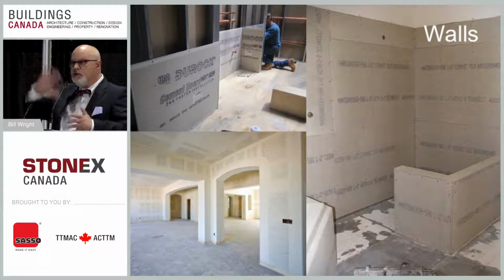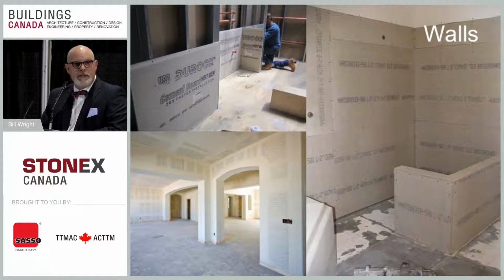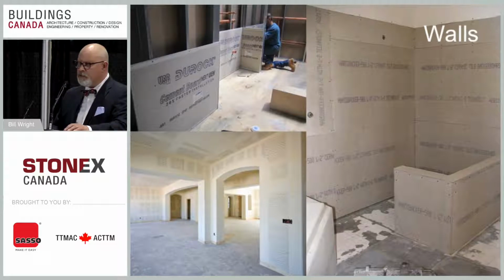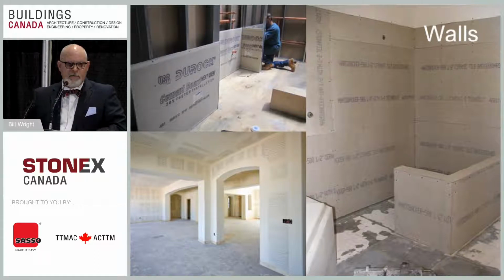I said, why didn't you parge the wall flat first so that you didn't have to cheat and use the spot bond method? And his question to me was, what was parging? He'd never heard of parging before, so I was a little astounded and explained to him what it involved. And we dismissed the tile contractor, and I'm just standing there with the general contractor. And I said, what was the story with the mosaics? When I just walked in, why are you putting the same thing down twice? He said, well, the first time they installed it, they didn't slope it to the drain properly, so they had to redo it.